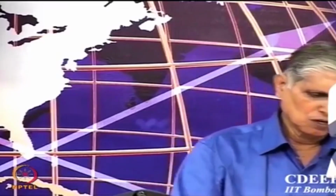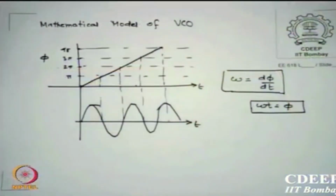A little bit of maths may be of interest, which we have already done, but I repeat it again for clarity. This is called the mathematical model of a VCO. We know if I write a voltage V equals Vm sin omega t or cos omega t, it has a unit of phase, that's omega t. So one can say that d phi by dt is essentially omega. The rate of change of phase is essentially the frequency or angular frequency.